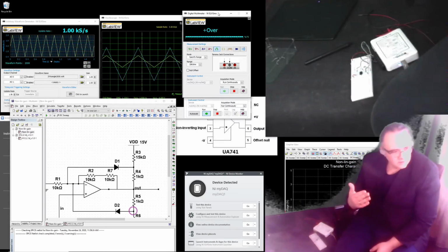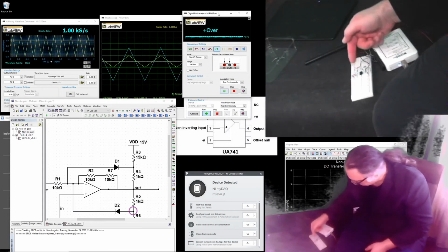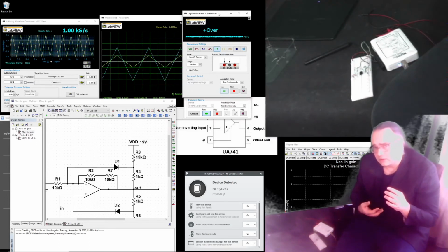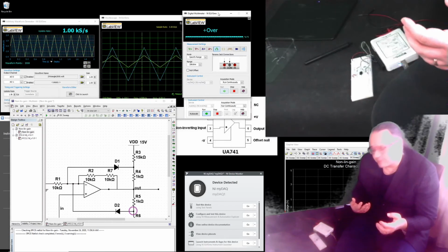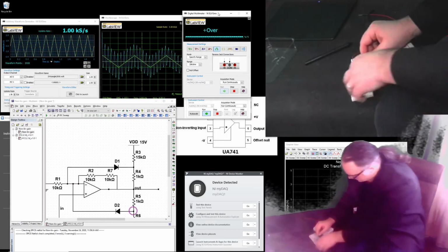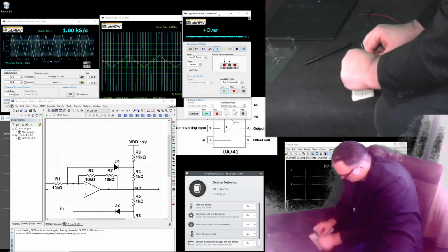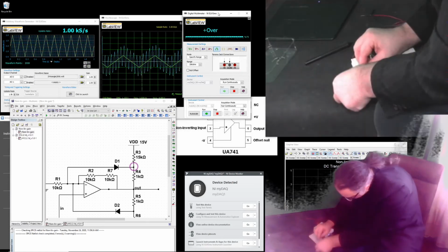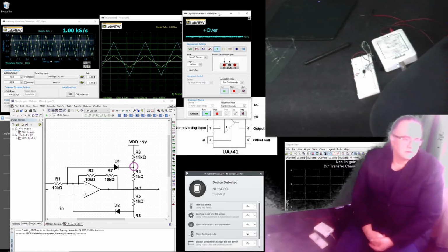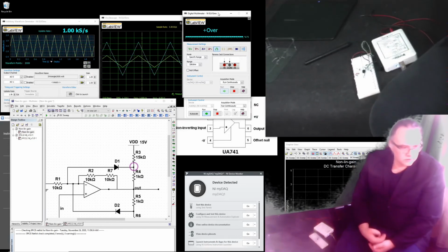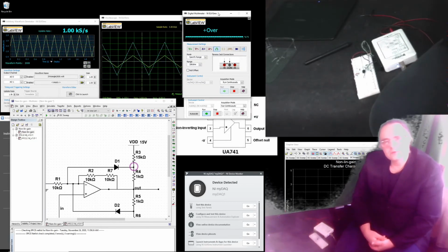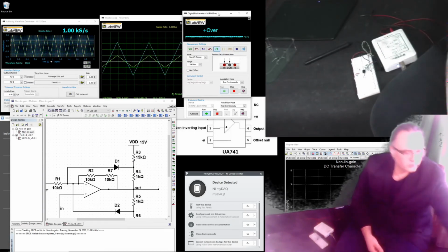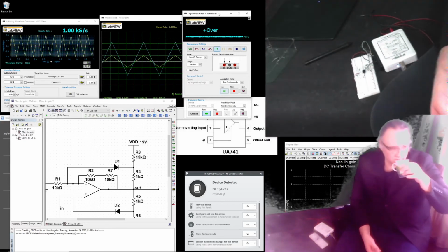So this will be the version which is scaled down because it's between a resistive divider, voltage divider between the output signal and the negative power supply of minus 15 volts. And this node here should be the equivalent, but for the positive power supply. Here it is. So this is the upper point of the voltage divider, and the other was the bottom point of the resistive divider.